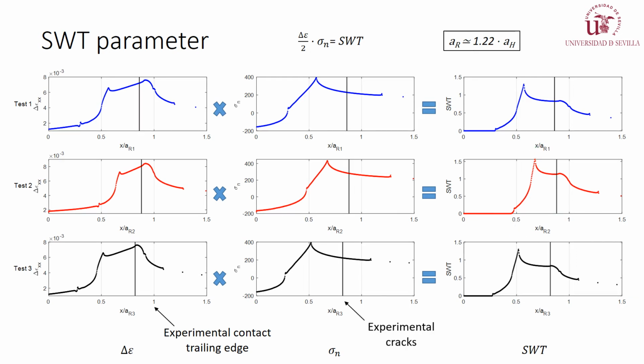In addition, the crack initiation point for each test is shown with a vertical line, where the cracks initiate, grow, and finally lead to a complete fracture of the specimen. You can see that neither direct stress nor Smith-Watson-Topper is able to capture the hotspot. Meanwhile, the strain range produces reasonable results.